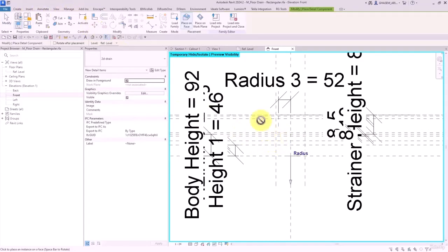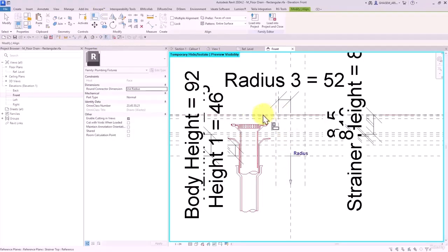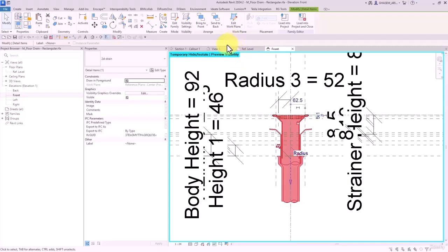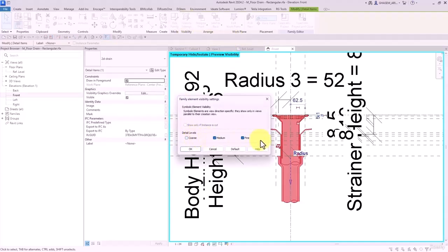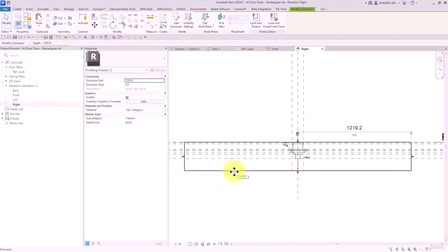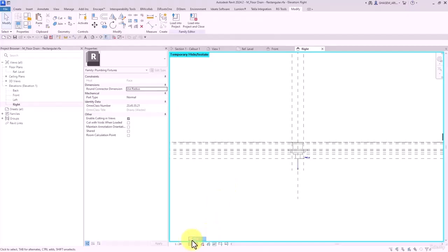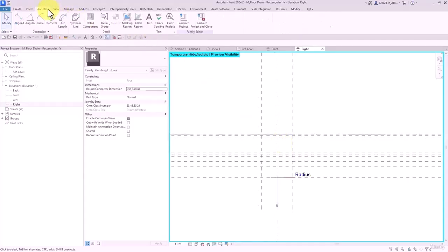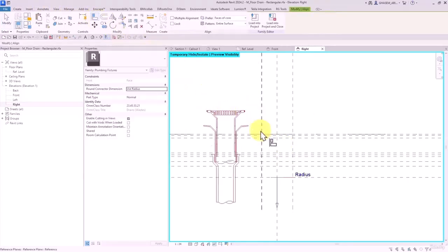So, okay, then this 2D detail which we made, I add a detail component, work plane, here, align the top of it with the top of this one and the middles, lock. Then I select this detail component, visibility. I don't want it to be visible in coarse. The opposite of the previous setting. Then here I select this, edge, fine, hidden line, and on. Okay, they are okay.